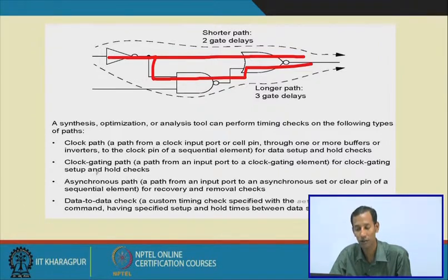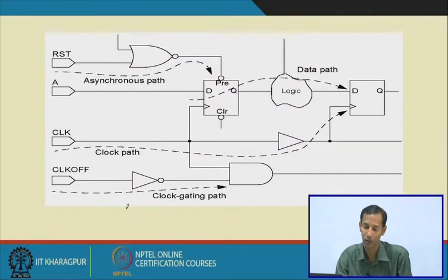Asynchronous paths are checked for recovery and removal violations. Okay. So these are the checks that are performed during synthesis and optimization.